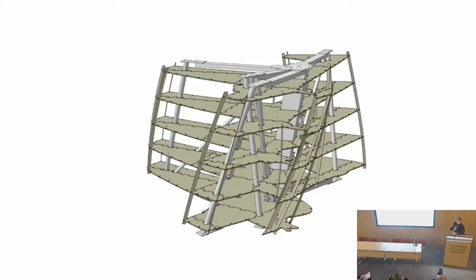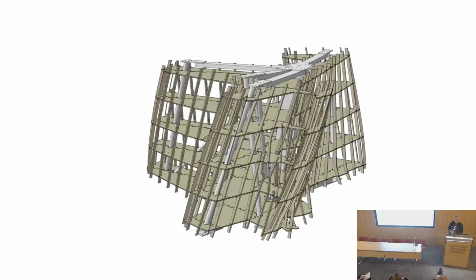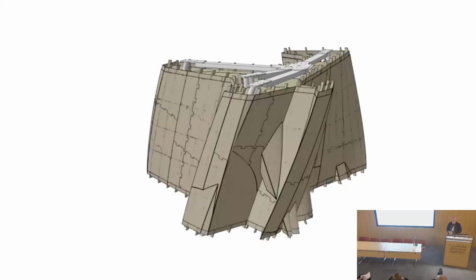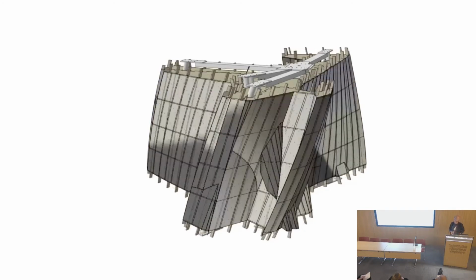It then has strips of plywood that define the corners, and then more strips of plywood. These are all planar, so these can all be cut from flat sheets of plywood, and these notch into the bulkheads. That gives you your load path and your ability to make a robust structure. Then you clad that in plywood to give you a stress skin on the outside, and finally it has the aluminium skin, which is the artistic surface of the piece.